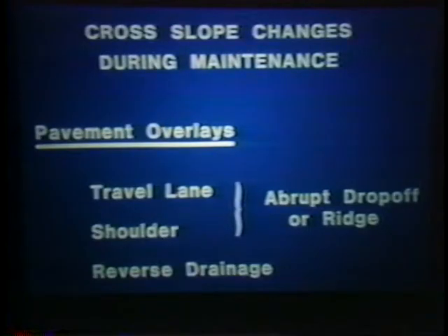When roads are repaired, resurfaced, or reconstructed, the design of the cross slopes are often changed. While the original cross slope adhered to acceptable pitch-over rate and drainage runoff, the construction work may make the new cross slope unacceptable. Overlays applied to the travel lanes and tapered abruptly to the shoulder will produce a much steeper cross slope differential. Thus, the pitch-over effect is increased.